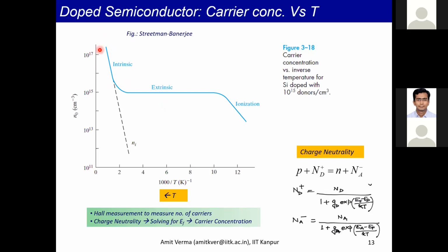Okay. So essentially, you can now control this carrier concentration by putting in different amounts of impurities inside your semiconductor. So this is one of the reasons we have to maintain extreme purities while doing fabrication of devices, and the materials we use in the fabrication have to be extremely pure, because a very, very small impurity like a parts per million can change the conductivity of the materials very, very significantly.